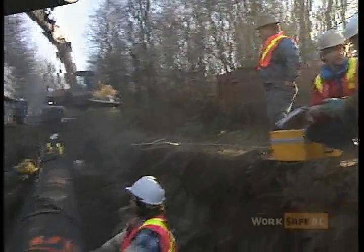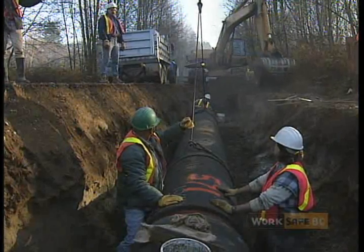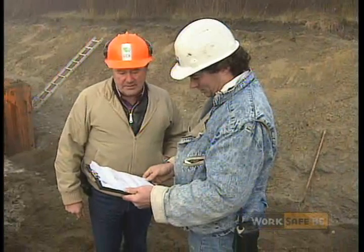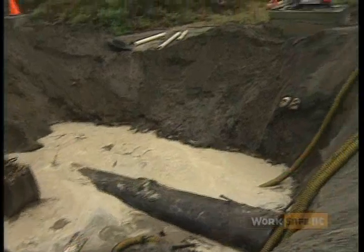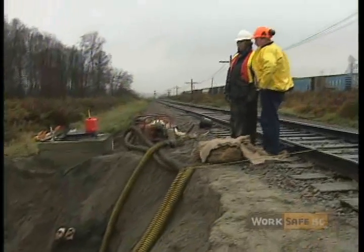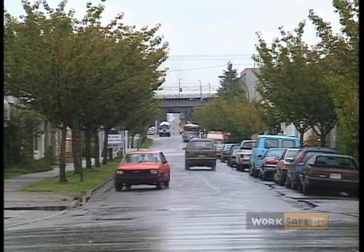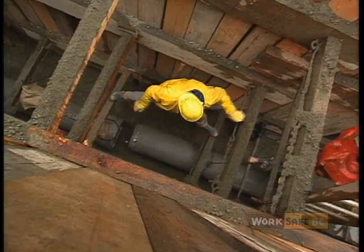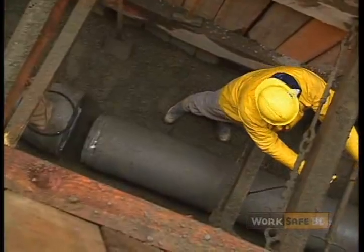There are rules that must be taken into account before work on an excavation begins. All excavation work must be carried out in accordance with the industrial health and safety regulations or with the specifications and requirements of a registered professional engineer. Utility services in the area, such as electrical, gas, steam, water, and sewer, must be located and assessed for hazard potential.